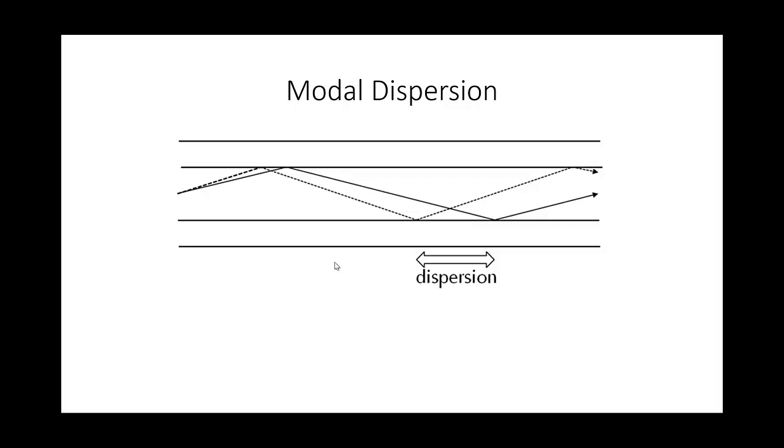Multimode fibre is typically 50 or 62.5 microns in diameter. It is usually used with 850 nanometer light from diodes. Because it's subject to modal dispersion, run lengths are restricted to hundreds of meters.